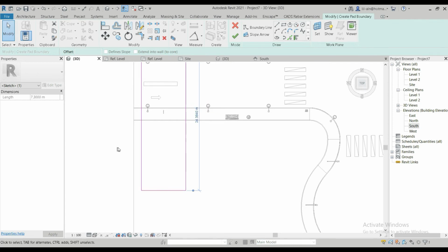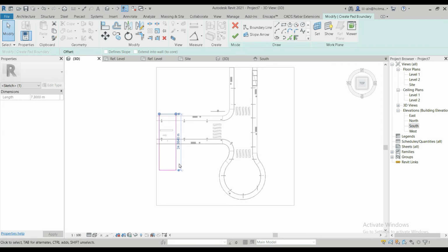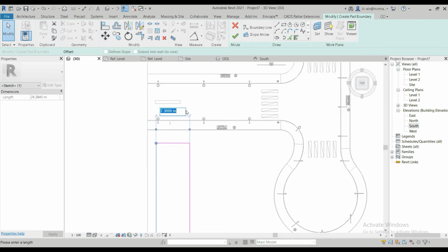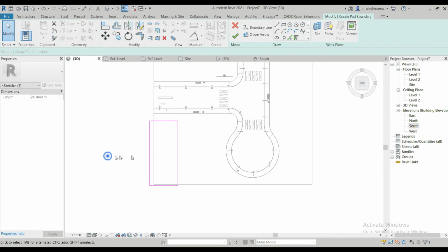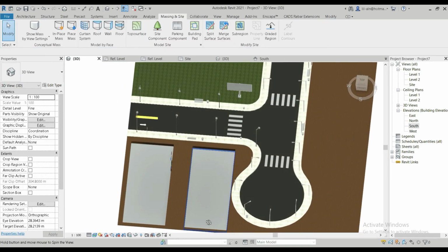Let's set this to 35 by 80 meters, and then we just move it to our position with the move tool, but it has to be within our topography. So I think we would have to increase the size of our overall topography so that all these plot sizes can fit inside. Now let's just move it to the right position. Okay, so this is our site plan.